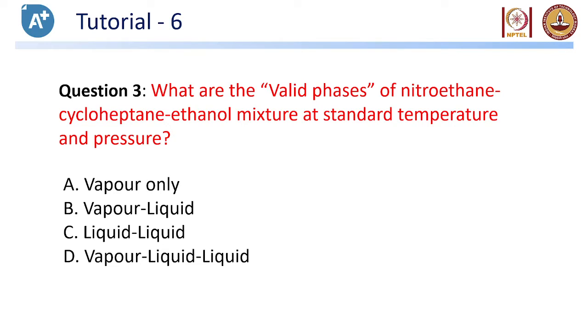The first duty for us is to find out whether the given system, obviously a mixture, forms an azeotrope or not. Then we need to see its state at various temperature and pressure conditions. After that, we'll be using non-ideal equations such as NRTL or Peng-Robinson, whatever suits your mixture setup. Based on that model, we'll try predicting whether it forms an azeotrope, whether it forms VLLE, or whether it shows VLE in the temperature and pressure regions.